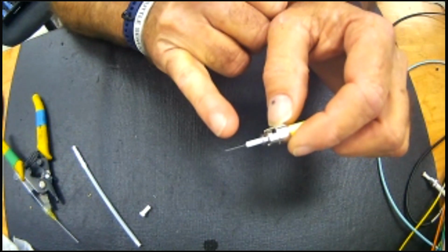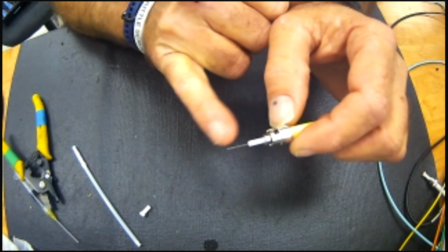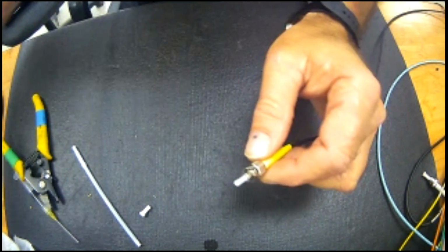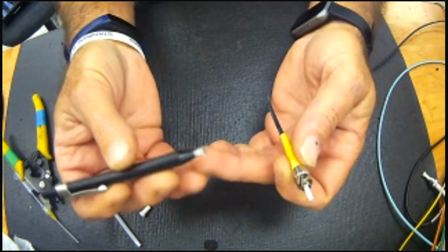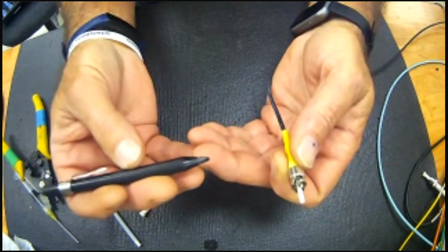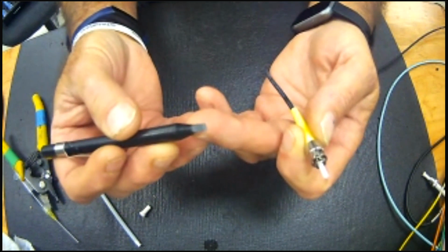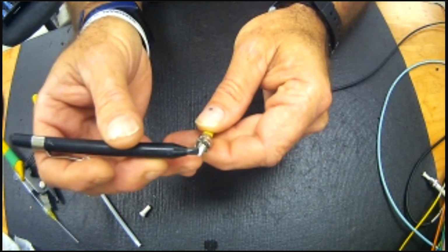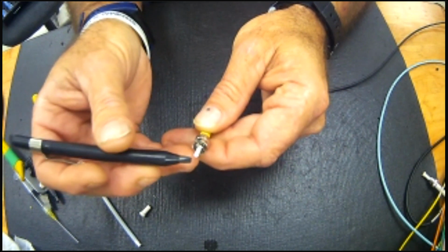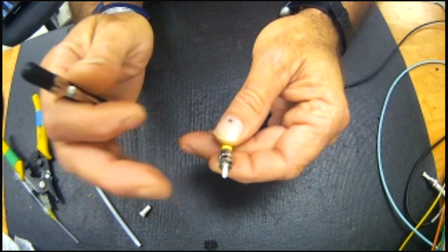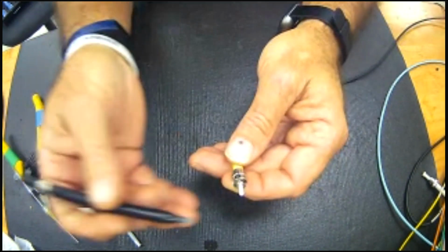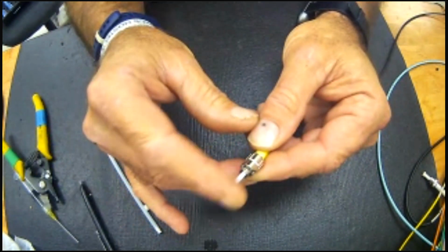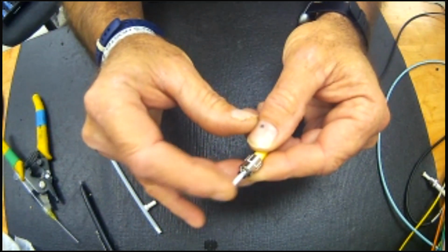Hopefully the camera can show you here a piece of glass protruding past there, the 125 micron. So at this point, you would need a scribe. You can buy scribes in diamond, sapphire, all kinds of craziness. This is just carbide, just plain old carbide. You would basically score the glass at the base and tap it. So you would tap it into a catch or a double adhesive area so that you can keep track of your broken glass. Now you've got a tiny little burr of glass on top.